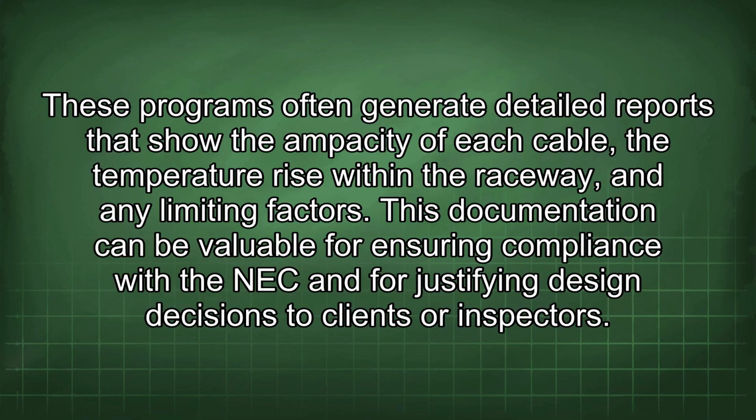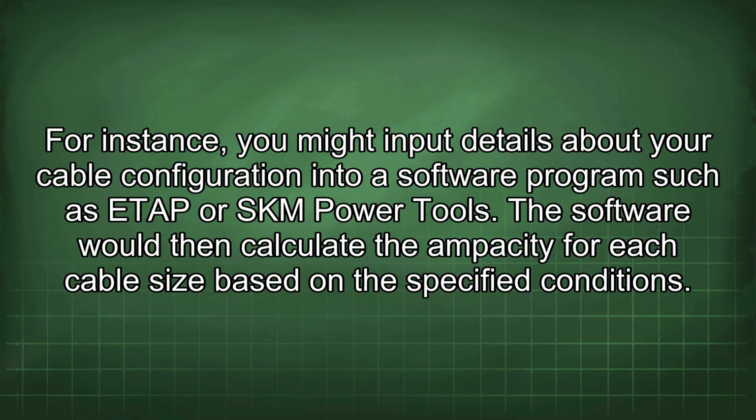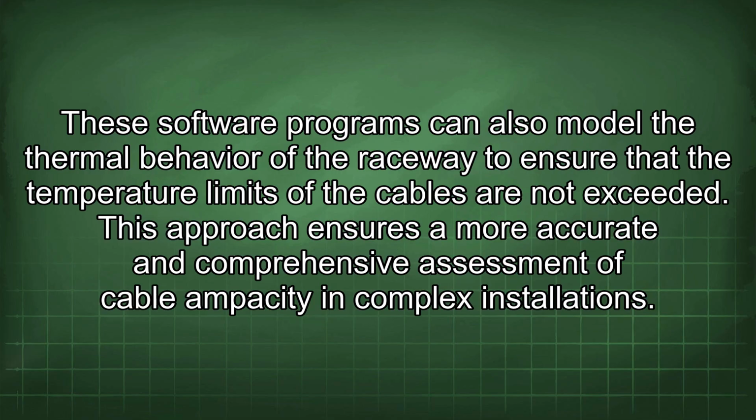This documentation can be valuable for ensuring compliance with the NEC and for justifying design decisions to clients or inspectors. For instance, you might input details about your cable configuration into a software program such as ETAP or SKM Power Tools. The software would then calculate the ampacity for each cable size based on the specified conditions. These software programs can also model the thermal behavior of the raceway to ensure that the temperature limits of the cables are not exceeded. This approach ensures a more accurate and comprehensive assessment of cable ampacity in complex installations.